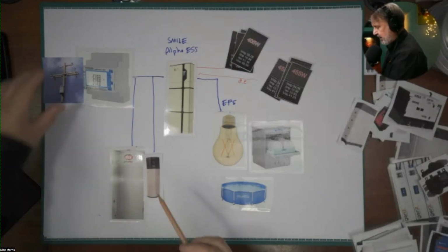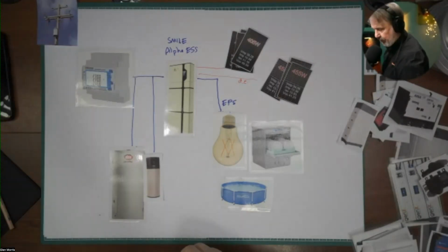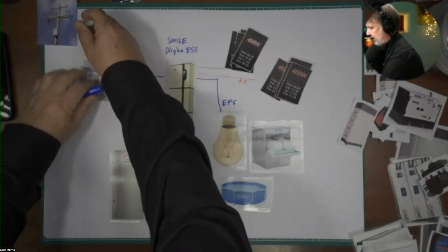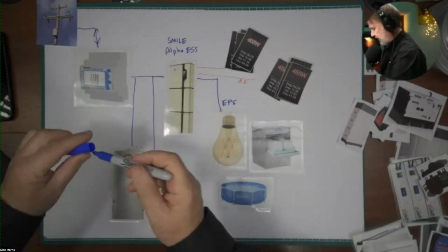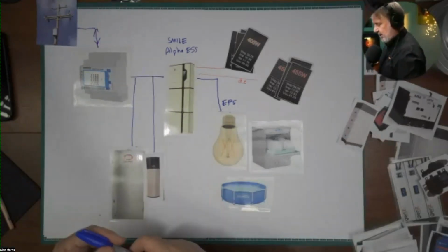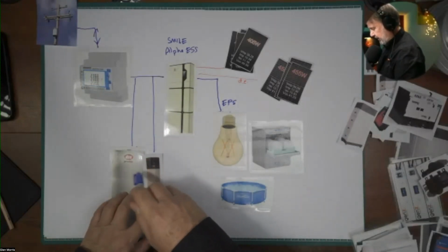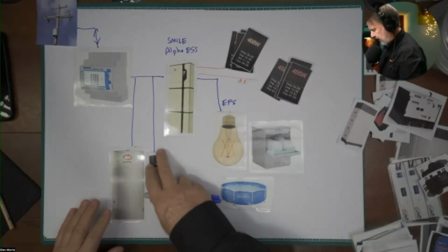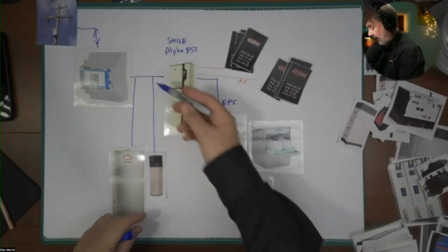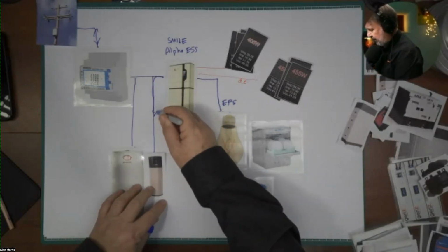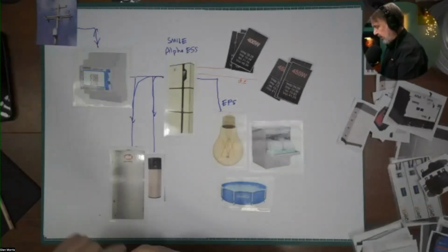How much energy are we sucking from the grid? So I might actually stick the grid right up there. And so we can draw one more line. So it's looking at the energy flowing from the grid. Is it flowing to or from the grid? And if it sees energy flowing from the grid, and it's because your grid-only loads, say a hot water service or a heat pump or something like that, are consuming power, it will try to displace the grid power by supplying energy to those loads at a rate to stop you drawing in from the grid.